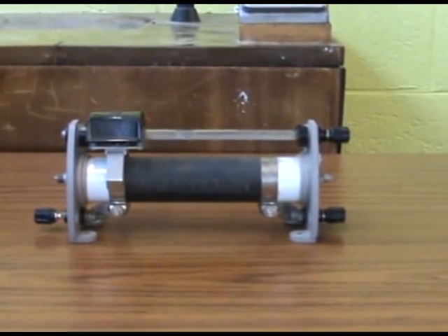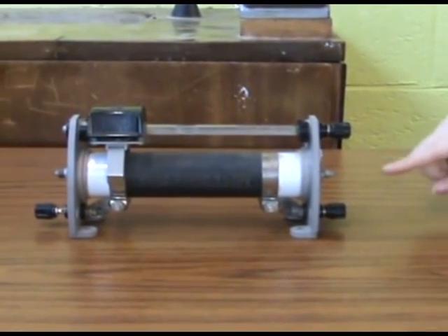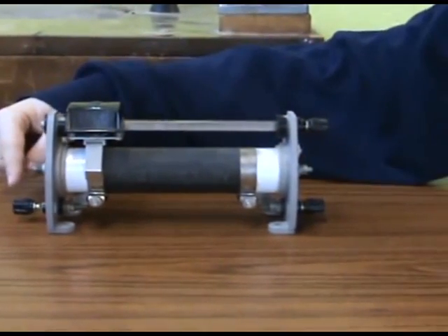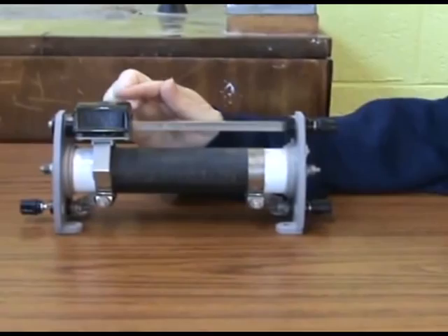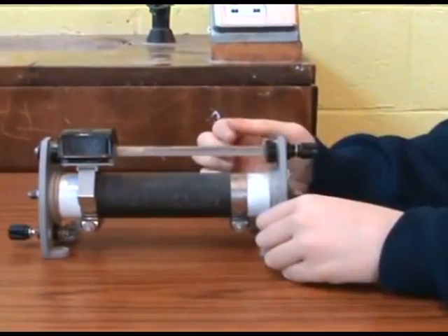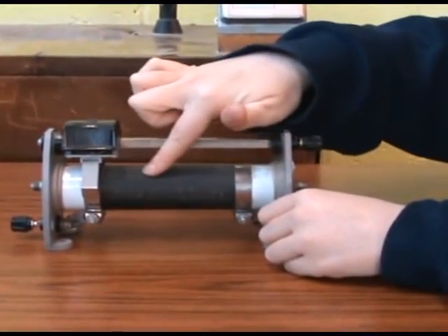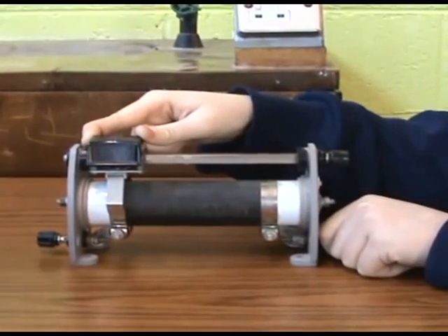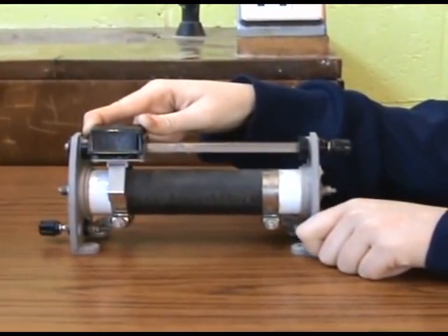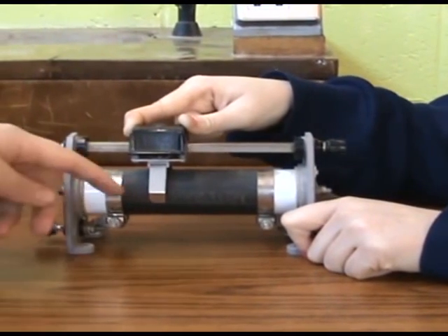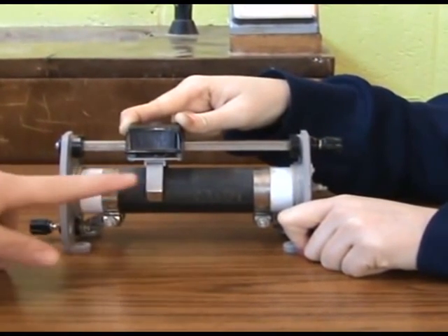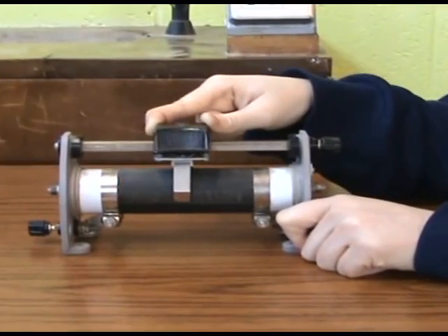This is a rheostat. It has 3 connections here, here, and here. It has a sliding contact connected to the first connection. It consists of a long coil of wire. The length of the wire between here and here is 0 and hence no resistance. When you move the sliding contact, you are basically increasing the length of the conductor and hence the resistance.